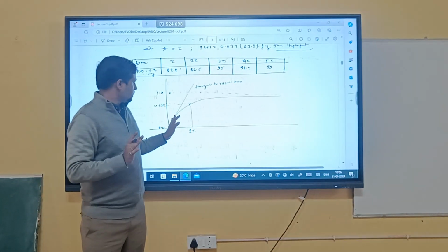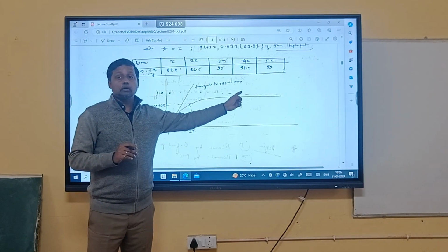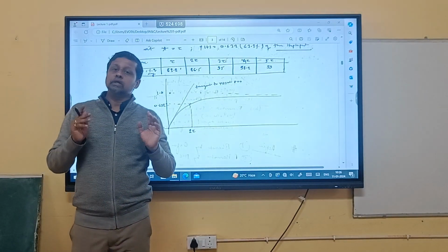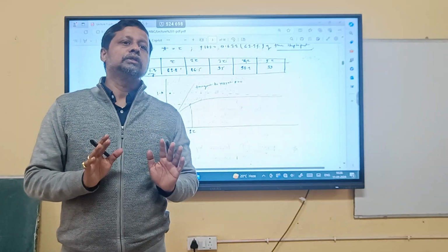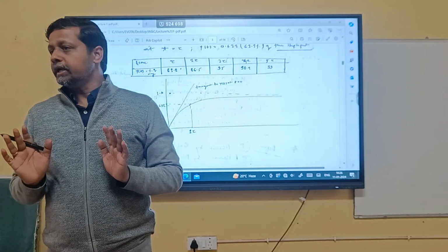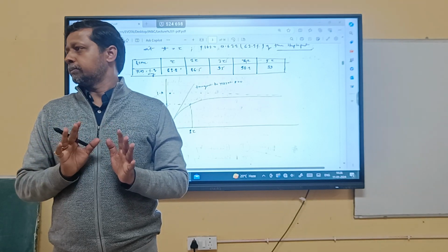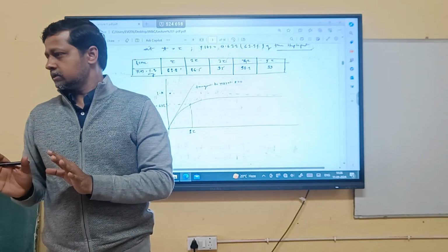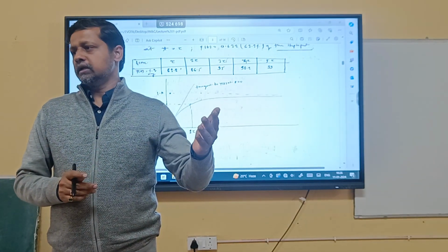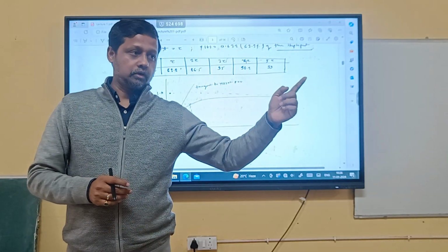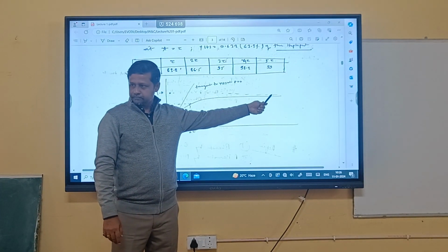Correct? So you need to compromise with that tolerance. That is not our issue. Now the point is what should be your tolerance band so that you will be able to recover your signal in a healthy way, so that your signal to noise ratio is acceptable. Okay? You know that we follow 2 criteria for commercial application: 5% tolerance, 2% tolerance. If you adopt 5% tolerance, your system will settle a little faster as compared to 2% tolerance. Remember, na? Let's say somewhere here is 5%. So 2% will be later to that.